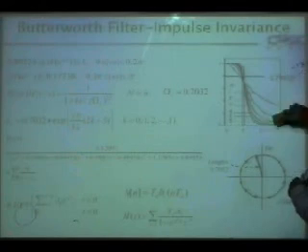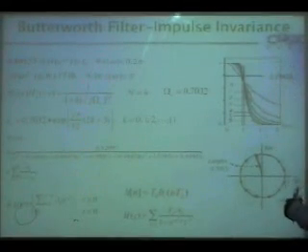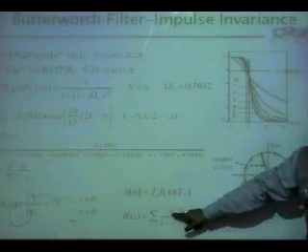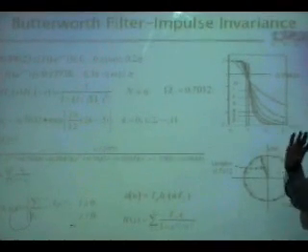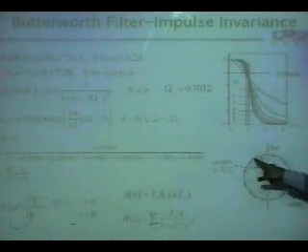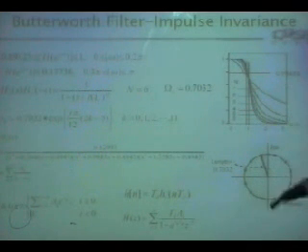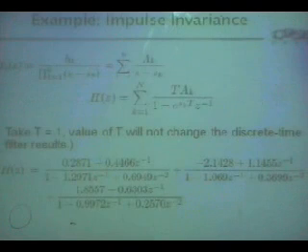And now we know, once you have all the poles, then you can plot by keeping T equal to 1. These are the partial fraction expansion and all that, but at the end of the day you get the same poles, but on exponential of s k on the unit circle. So this is the process you go through to design a Butterworth filter.